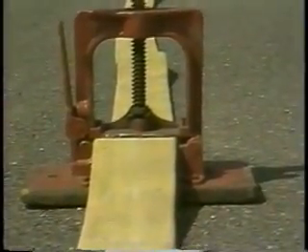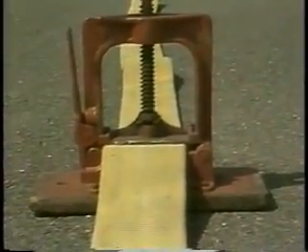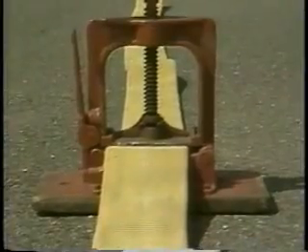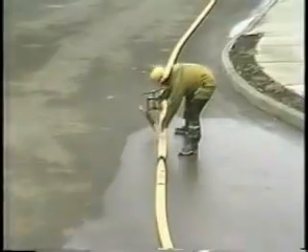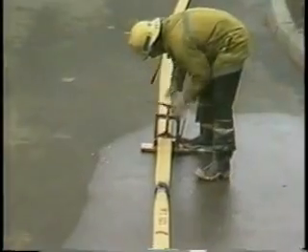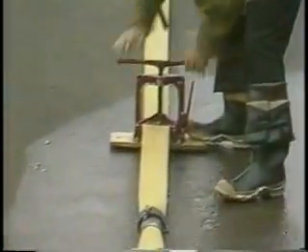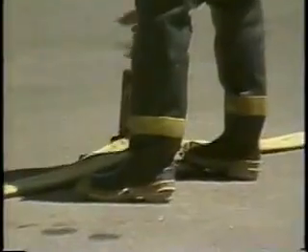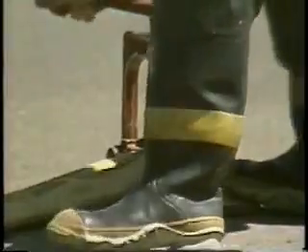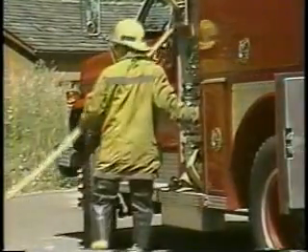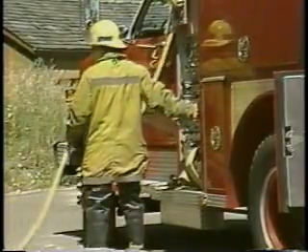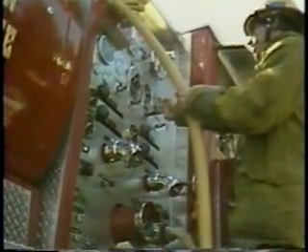Clamping the hose prevents the hose bed from being charged with water and protects the apparatus pump from receiving water before it's been properly prepared. With this type of hose clamp, it's a good idea to stand opposite the hinge of the clamp. If the supply hose is charged while you're putting the clamp on, the clamp will not fly back against your leg. After the clamp has been secured, the driver can return to the pumper to start the water supply for the attack crew from the booster tanks.